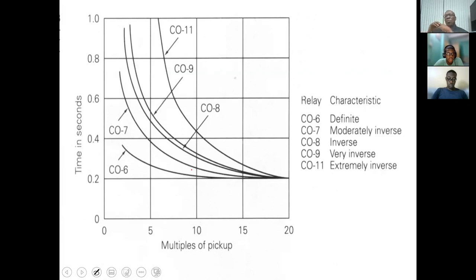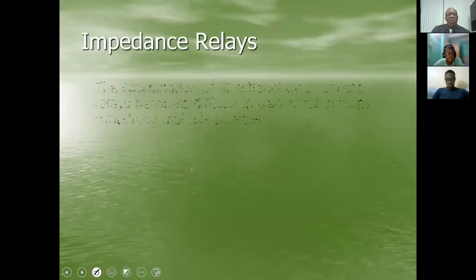And so you wouldn't want to have the CO7 operating with a fuse because in terms of timing and ensuring that there is some amount of coordination between them, you want to have the operating curves quite similar. All right. But again, don't get overly worried. We'll come back to these operations and the various calculations in detail. But I hope that we will get to some of that this evening.